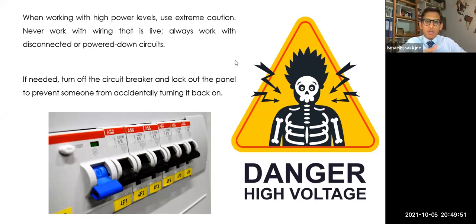You were trying to work your way in with your Raspberry Pi, preparing for Diwali, whatever, and this is bad for you. So at times you need to lock it or put a notice there: work in progress, don't switch on. For us in power systems, we intervene on high voltage lines and we put a lock, lock and key, and we have the notice, because it's so serious. We have seen people lose their life from silly mistakes. So just be careful and be serious, and consider all these safety precautions when you're working.